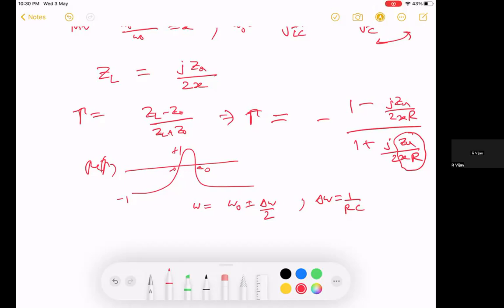That's what it was asking you to do, and do the same thing for the imaginary part of the gamma reflection coefficient, and that goes to plus and minus 1. So when you turn it into the phase, if you remember, I told you that at resonance on reflection for a resonator like this, the phase goes from plus 90 to minus 90 degrees. So that's basically what the problem wanted you to work through.